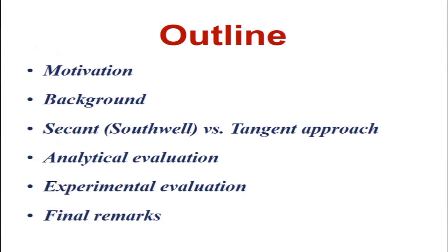We're going to go through the motivation for this study, some background information, and then probably spend most of the time talking about two different approaches that we're contrasting in this study as to how to determine buckling loads for experimental cases where you, in fact, could not reach the buckling load in the specimen because you run out of capacity in the testing machine or in the testing setup. And that's, in our particular case, as we're going to see, because we're using fairly large specimens.